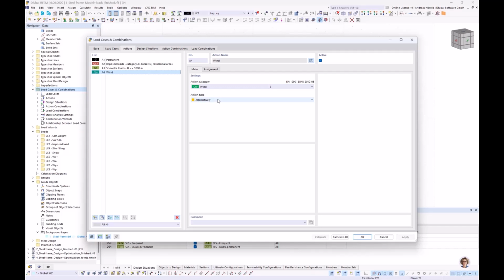Only one of the action's load cases can be effective in the combination, as it is for the wind load cases when they come from different directions. And differently means load cases can be assigned to groups. Load cases act alternatively within a group, and load cases in different groups can occur simultaneously.